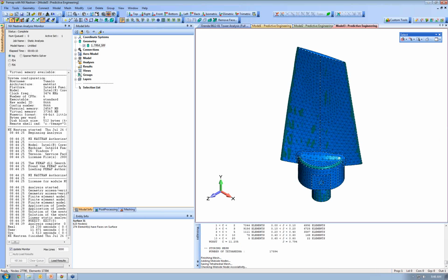So that tackles the first 4 or 5 steps of our workflow and kind of condenses it down. Again, that works with any sort of workflow you're going to use. If you've got a solid model, you go straight to Tet Mesh. It'll create a property. It'll set the sizing. It'll do everything for you kind of automatically. And if you're not really worried about having absolute control over each of those steps along the way, it's a way to save some time.